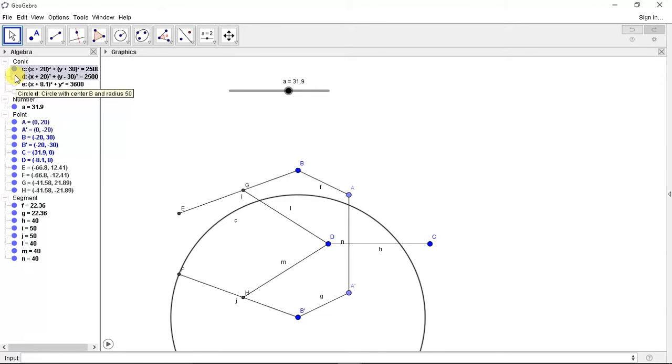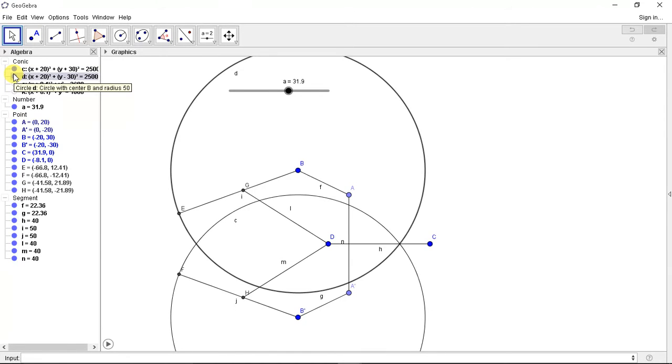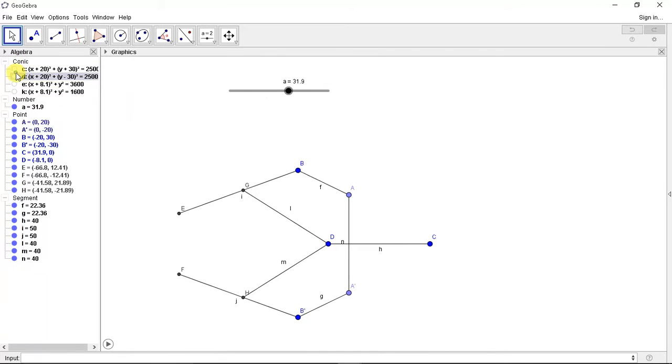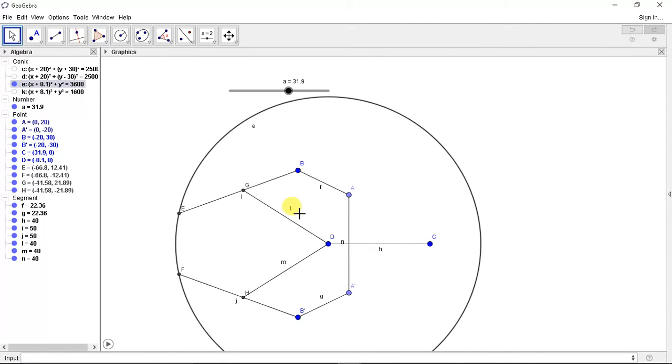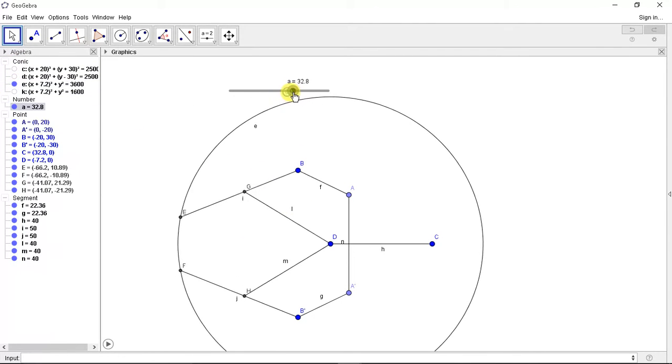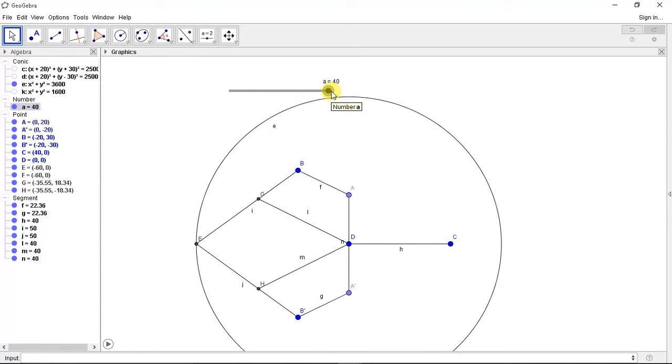We'll draw 2 circles which will be equal to the link length as their radius, and then after this we'll define a circle such that when the point is at the extreme position, both the arms should come to the same point.